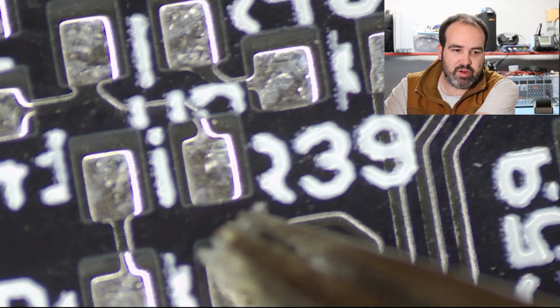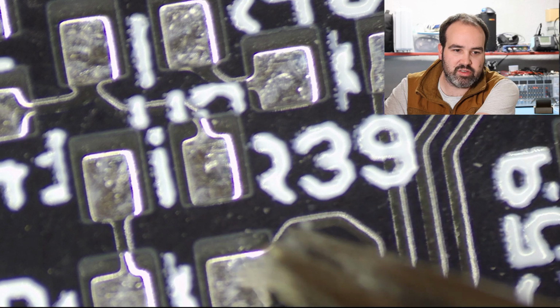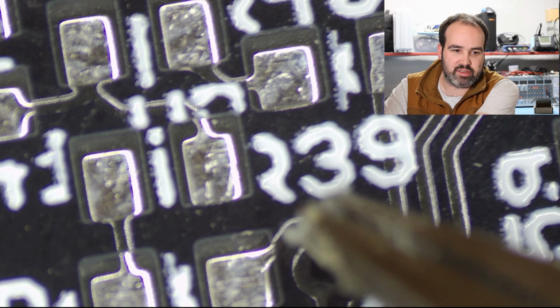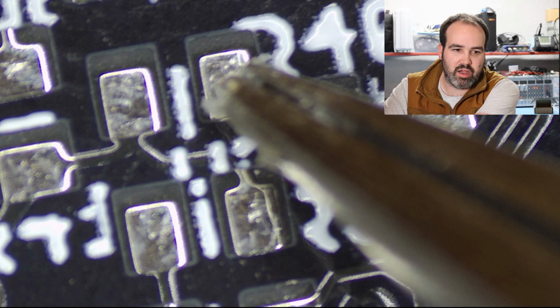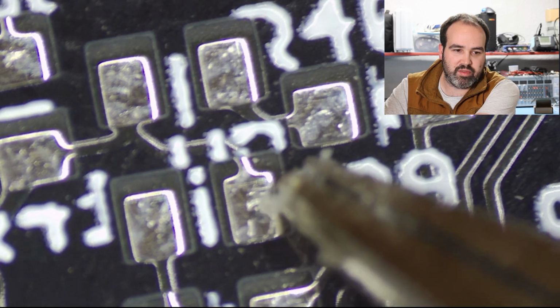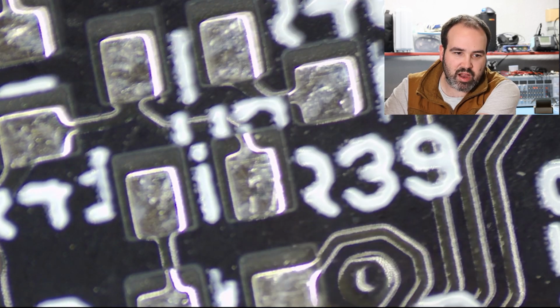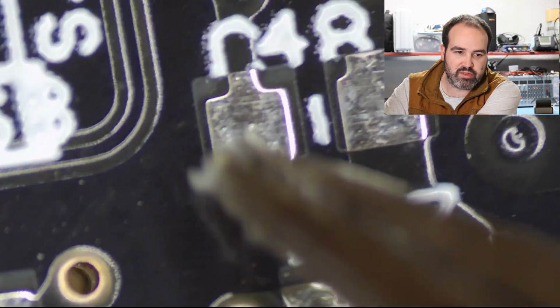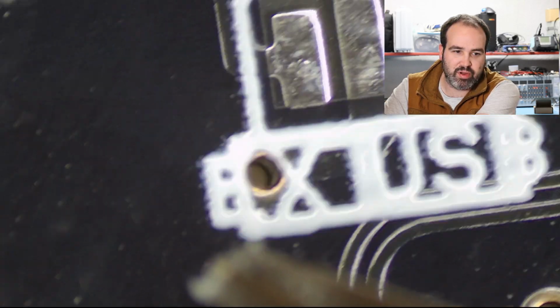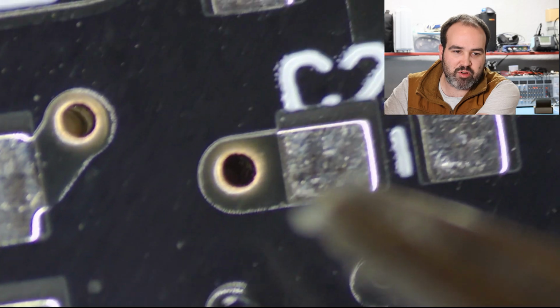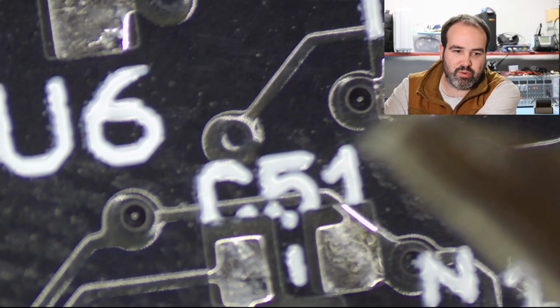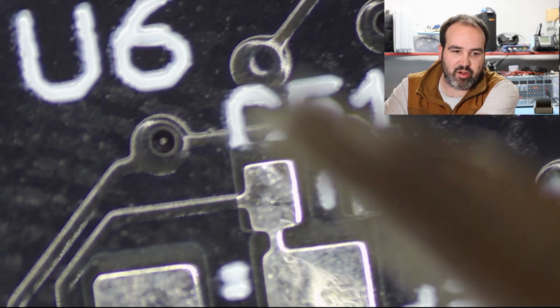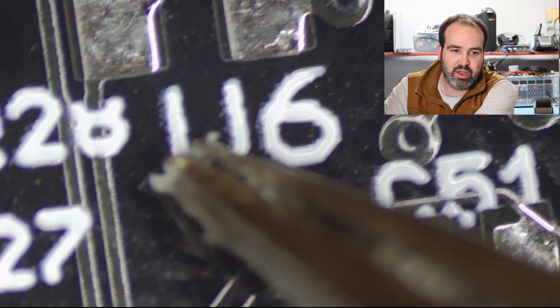And I say that because if you notice here, a bunch of these are cut off. Like this should say R40, but it just says R39. The R40 is cut off there because the silkscreen gets cut away from the solder mask openings, right? Because that would be bad if it went over. So the PCB fabs will almost always do this for you. It'll be an error, but they'll most of the time cut it back for you.